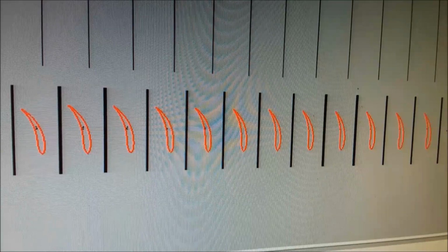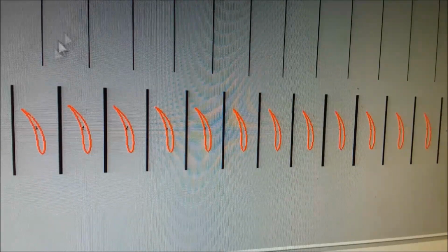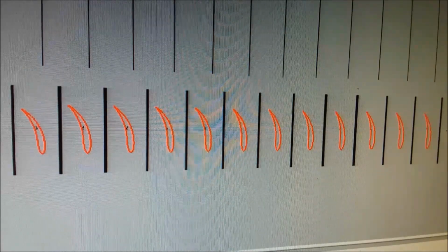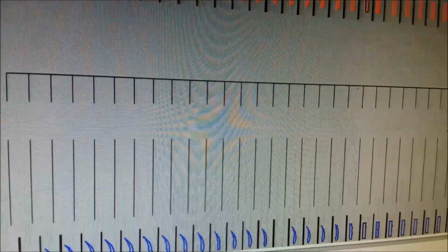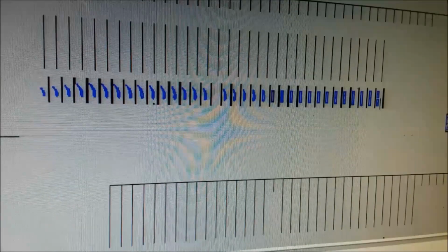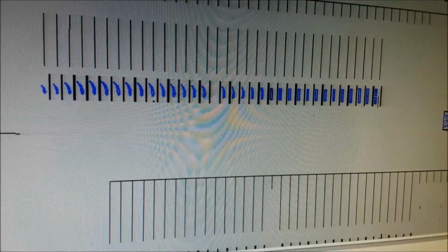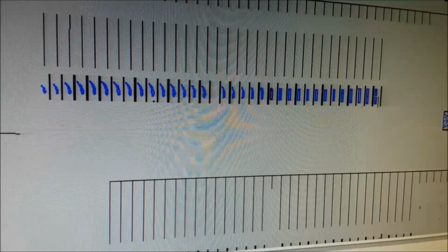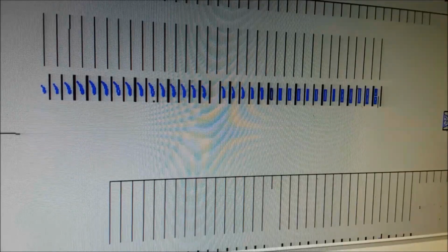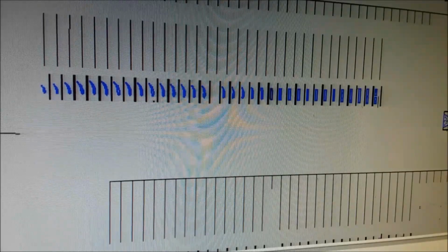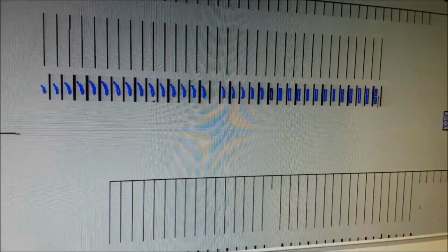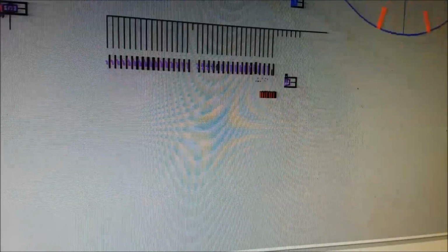These are fan blades sliced into things an inch apart, and you can basically cut pieces and then stack them up and sand them. Not a real efficient way of doing it, but it gives you a chance to see how it's changing shape from one end to the other, if nothing else, to find out if all of it has got the angle of attack you want. You might want to flatten out the ones at the tip and put more angle on the ones in the center. But that was probably 2 years ago, and that's the blades that it came off of.